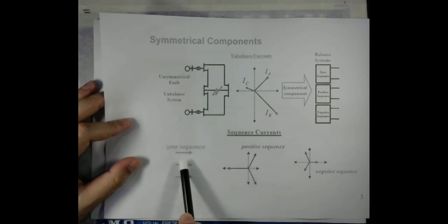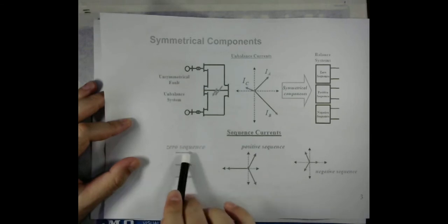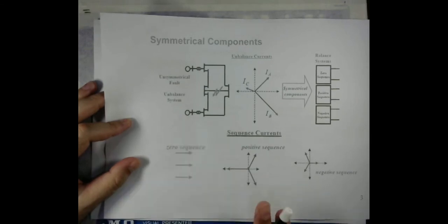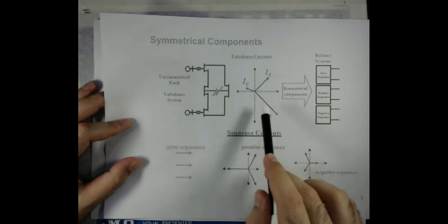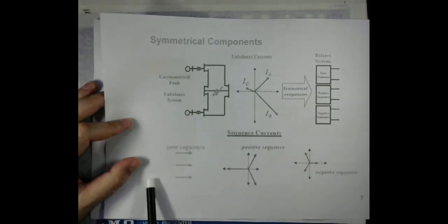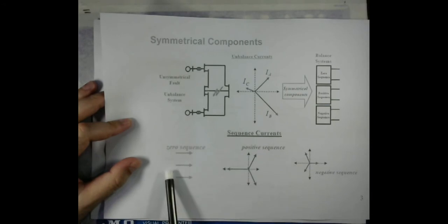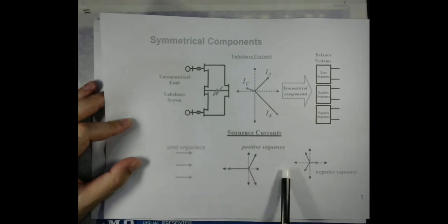And similar is the case of the zero sequence quantities. In one sequence, all three components have equal magnitude and are phase shifted by 120 degrees. In case of the zero sequence, they have equal magnitude and are in phase. That's why after decomposing using transformation into these three sets of components, these are balanced quantities, known as sequence quantities or sequence components.